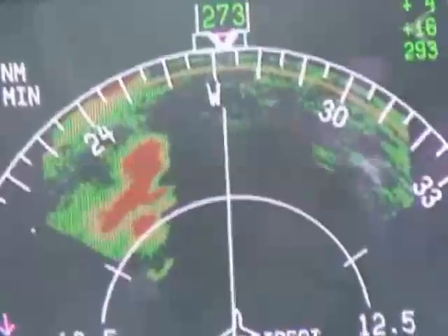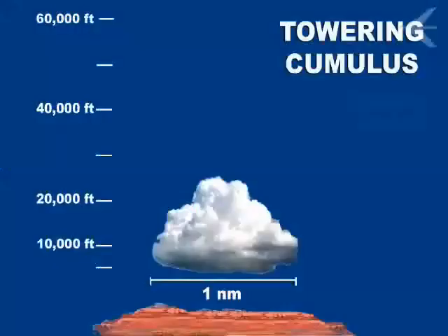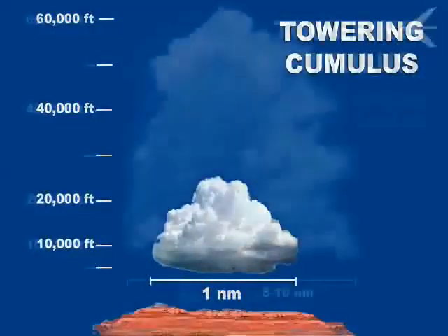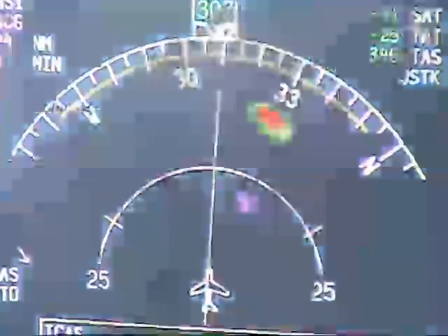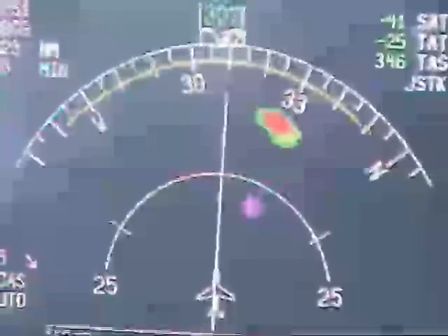While a single thunderstorm seldom lasts more than an hour, a squall line can contain many storm cells developing and decaying over a much longer period. A single cell can start as a cumulus cloud, only 1 mile in diameter, rise to 1,500 feet, grow within 10 minutes to 5 miles in diameter, and rise to 60,000 feet or more. Therefore, radar should not be used to take flash pictures of weather, but to keep weather under continuous surveillance.